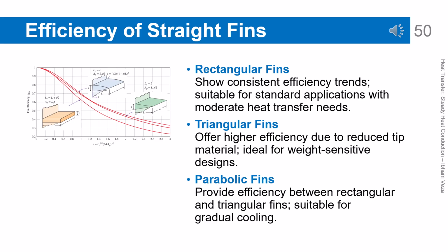As fin length increases, efficiency tends to decrease because the tip region becomes less effective. Profile selection is a trade-off between thermal performance and material usage. This analysis helps determine the most optimal shape for a given application.